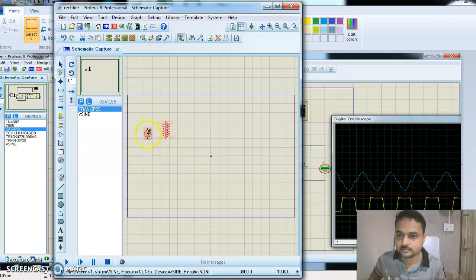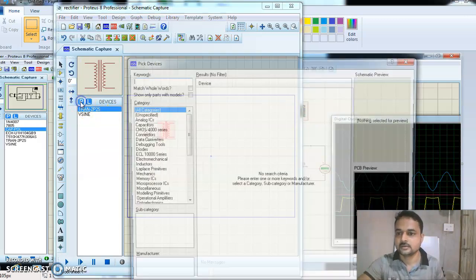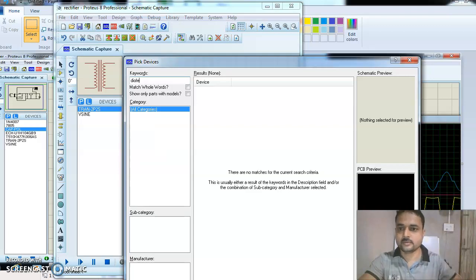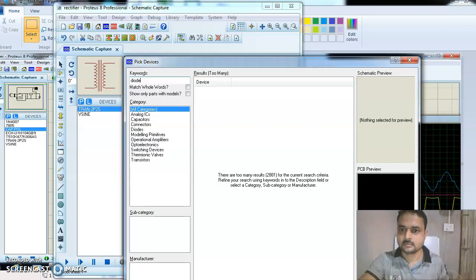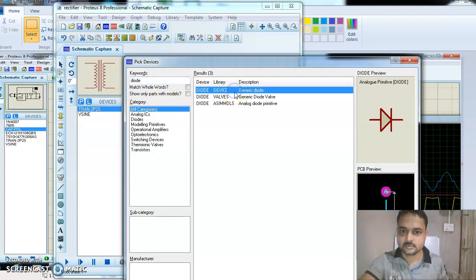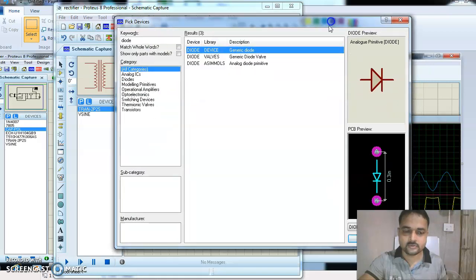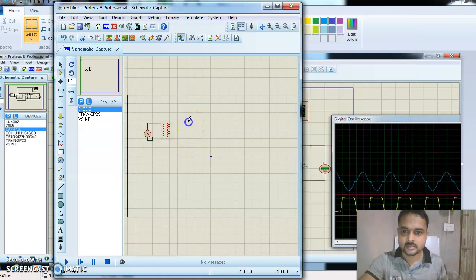You have to connect this component like this, and you have to select the diodes. Okay, what diodes are required? PN junction diode, generic diode is here, and analog devices. This diode you have to select here, click here, and put this diode here. So how many diodes are required? 4 diodes. We have to make the connection in such a way that...